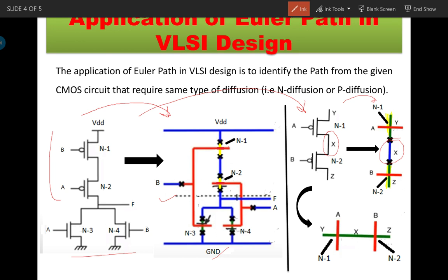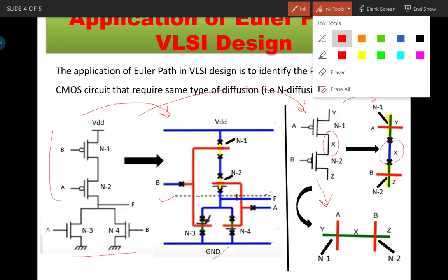So we should have few electrical problems, and also the area should be minimized. Now if we join the two diffusions with the metal contact, it will require a large area on the wafer. We have a number of transistors connected either in series or parallel, and if we go on connecting each diffusion with a metal contact, the overall area required for the circuit construction is more. Now how do we overcome this problem? For that we use another concept, shown in the lower portion.